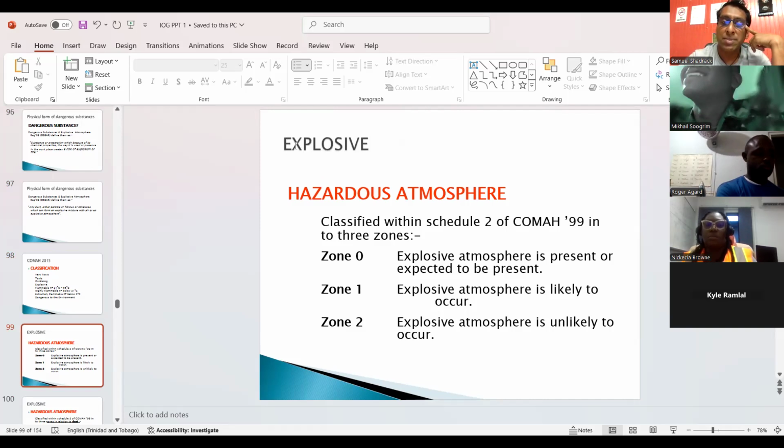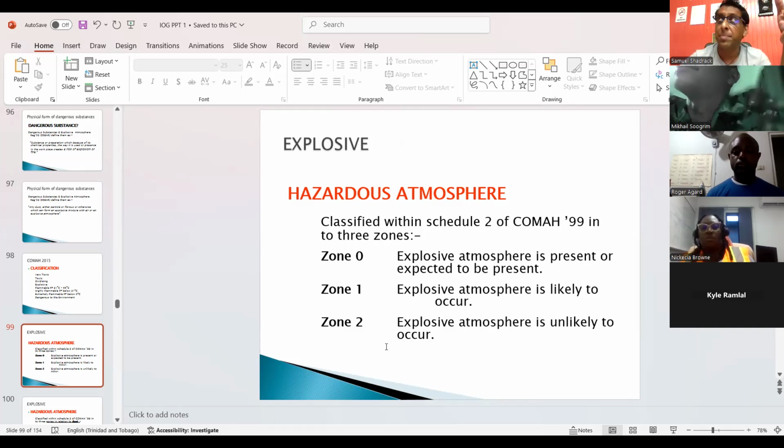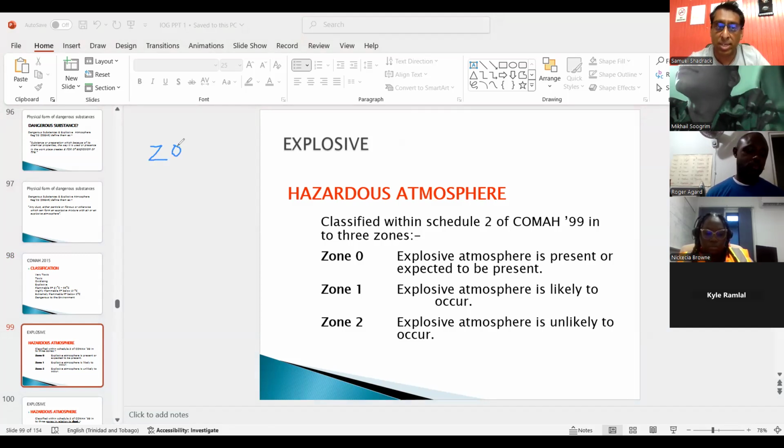For those who did process safety too, that same law, COMAH, required the employer to zone the areas. This is a nice question, where a worker may be exposed to a flammable gas or a hazardous gas or dust, right? They have two zoning systems, and the other one is on the other slide, so bear with me a bit.